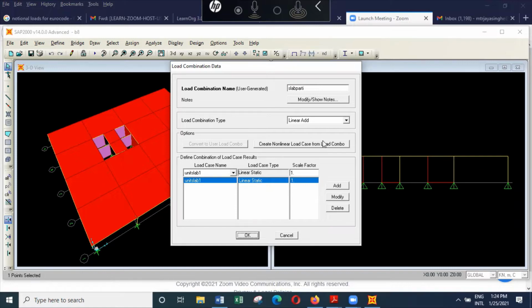So you can look at Eurocode, the initial one, part 1 dealing with loads, and you see that when you have lightweight partitions, they allow the lightweight partition load to be represented as a UDL on the slab. So the values are 0.8, 1.2, and there's another low value also, like 0.5 kilonewtons per meter squared. So I have allocated 1 kilonewton per meter squared here.